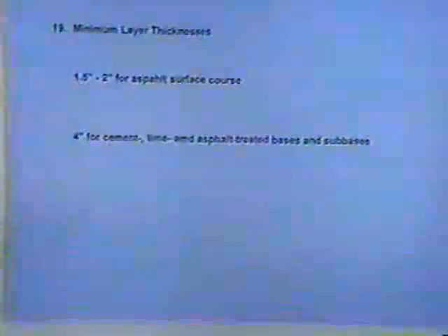And when you get into actually using some of these things, I'm nearing the point where I'm going to stop today. When we start looking at pavement design, we start talking about really how thick the pavement has to be. And I notice a spelling error on this particular slide, but we'll talk about the base, the sub-base, and then the pavement surface itself.